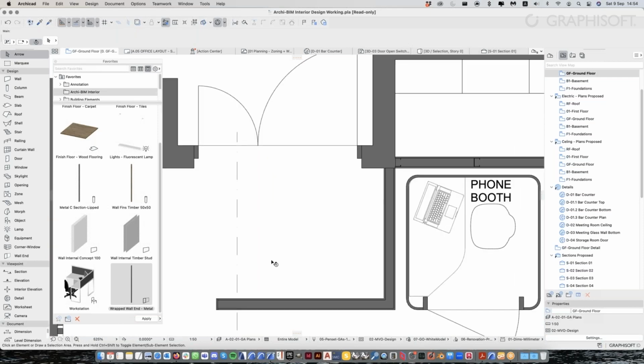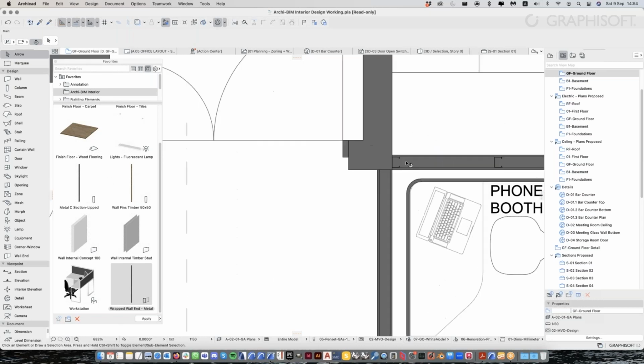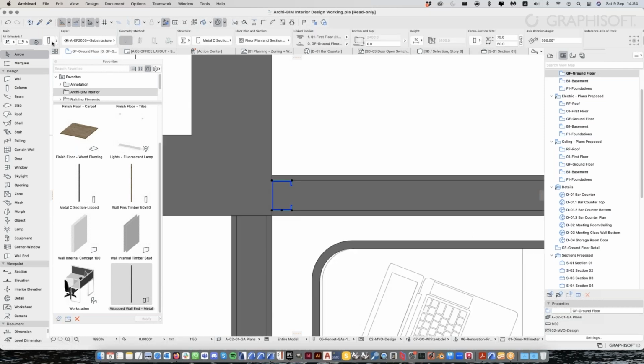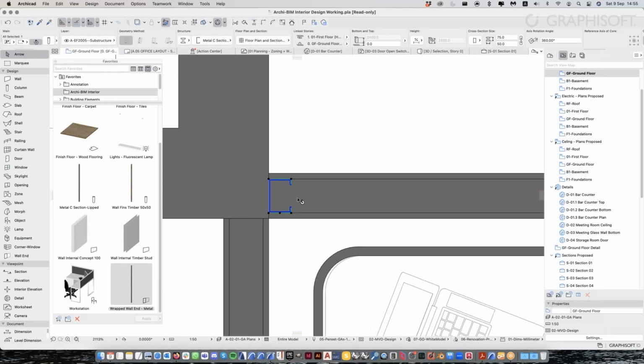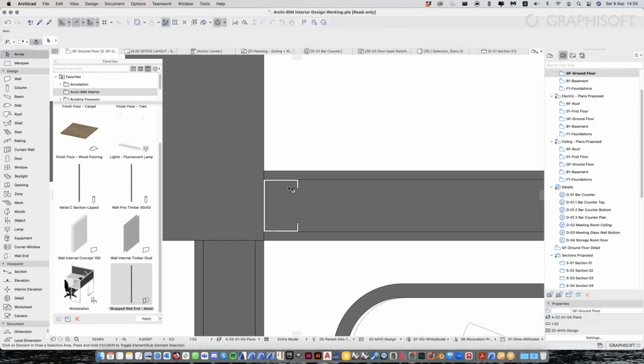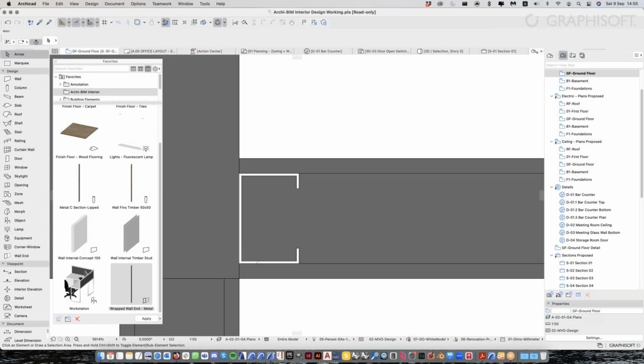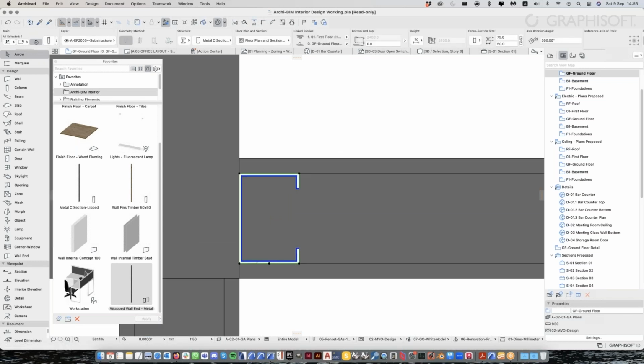So then, as I said, I'm going to start building the studs. So what are these studs? We are actually using the column tool for this. Instead of a wall, imagine if you did a wall, you would have to draw a very thin one and create this kind of C shape.